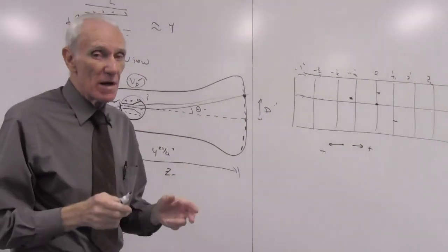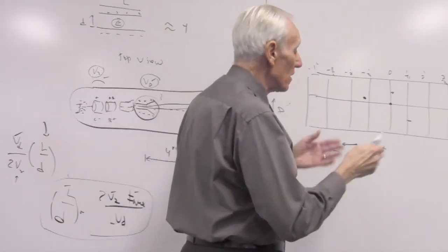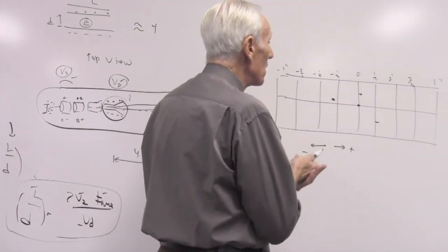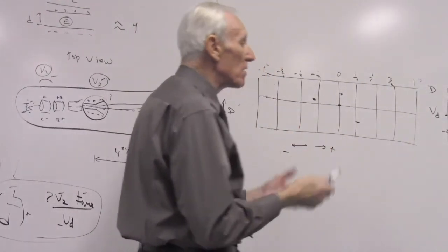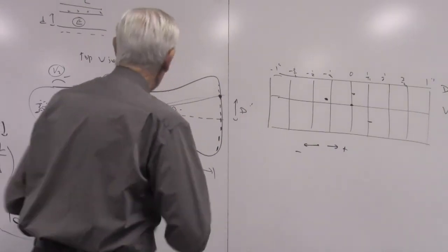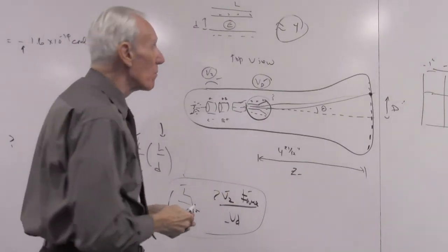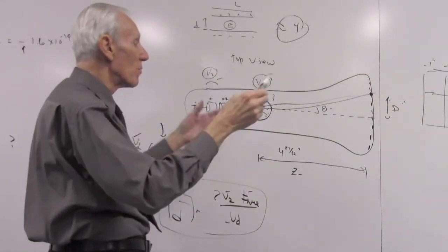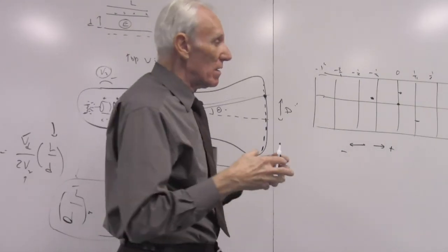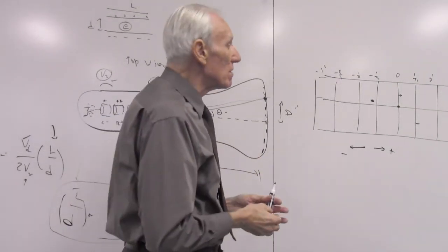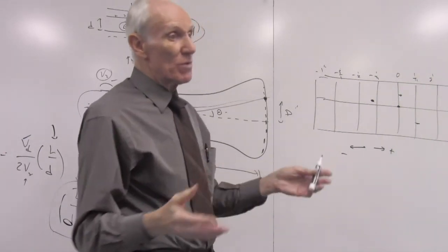We are going to get the right answer. So if you add up your errors, such as we'll talk about, of reading the meters, typically, you will get a certain percentage, and all you can do then is say that my L over D ratio, which is probably going to be somewhere around 4, ballpark of 4, 3.7, 4.2, whatever it is, is accurate to within, in the example that we will talk about in the lab, accurate to 3%.